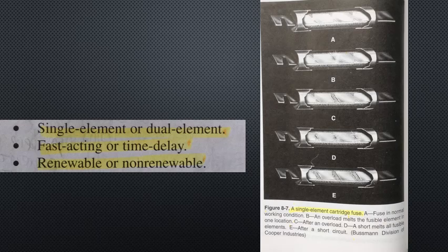Fuses. Fuses are highly reliable and safe overcurrent devices. They consist of a resistance-sensitive link encapsulated in a tube. The ends of the fuse are connected to contact terminals of the conductor. The link has a very low resistance. If high current occurs, the link melts and opens the circuit.